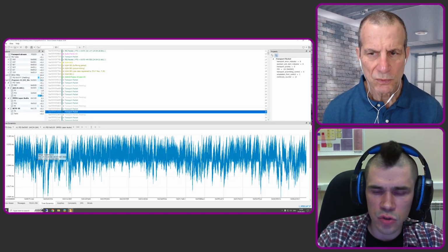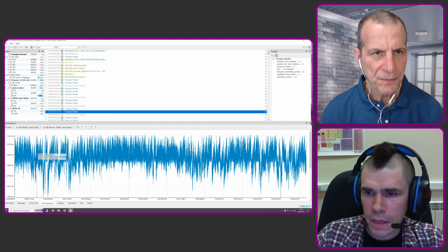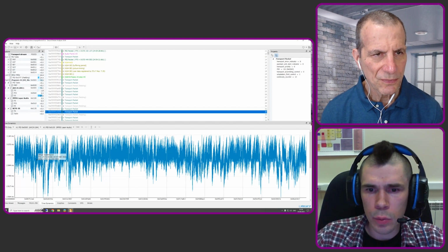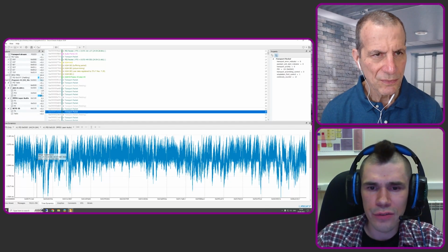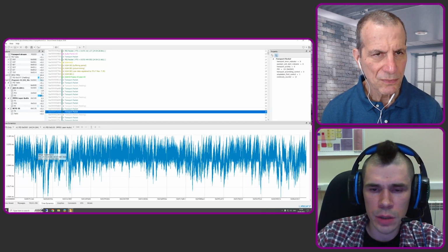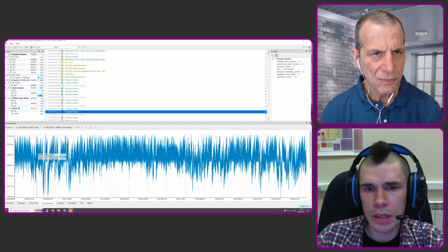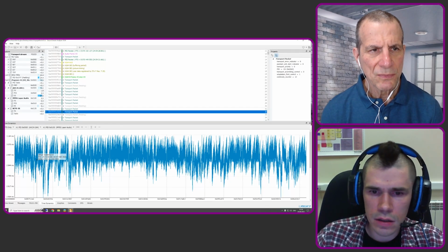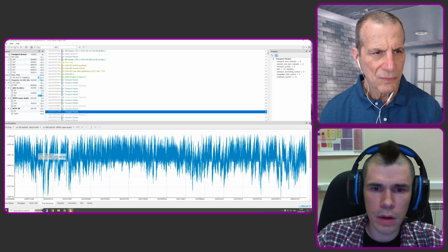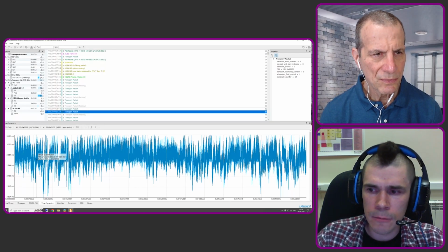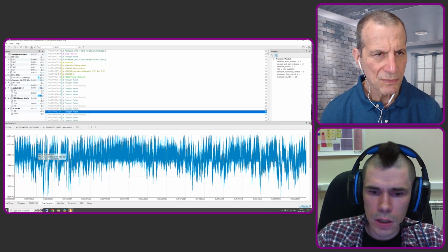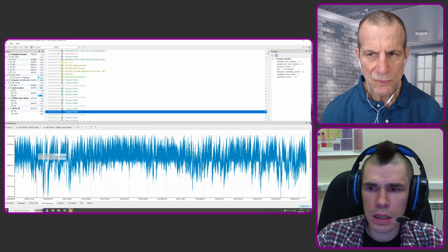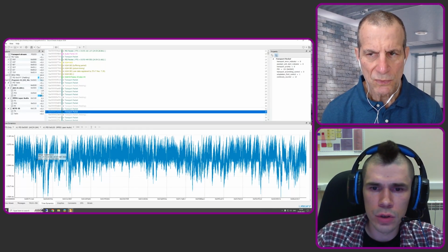With such a stream, a typical modulator will wait up to 1.5 seconds of the stream, and then it will start skipping the data. That will lead to a lot of errors in the log of the modulator or multiplexer. And the viewer will see it as video artifacts and video-audio lip sync issues.